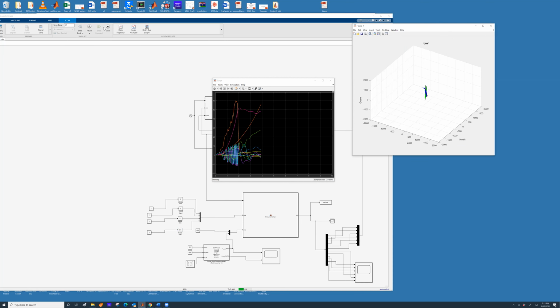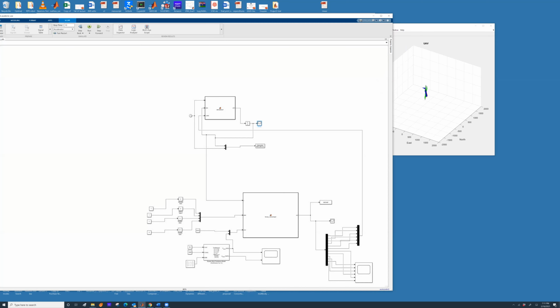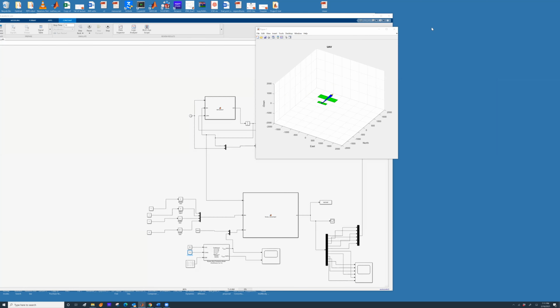For example, this VA, airspeed, is not right. Zagi will never go to 1000 meters per second. So you change this airspeed, and what would help you is the reference that I gave you here. This reference will tell you what the typical parameters are that you can expect on the Zagi frame. And then you should be able to see and upload a very clean, nice working simulation.